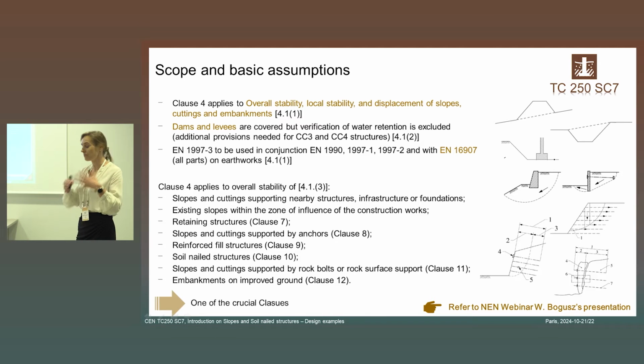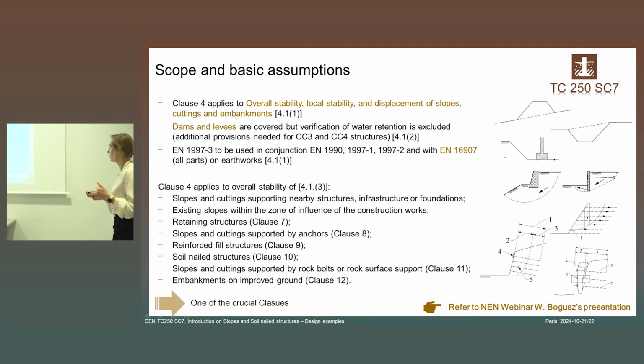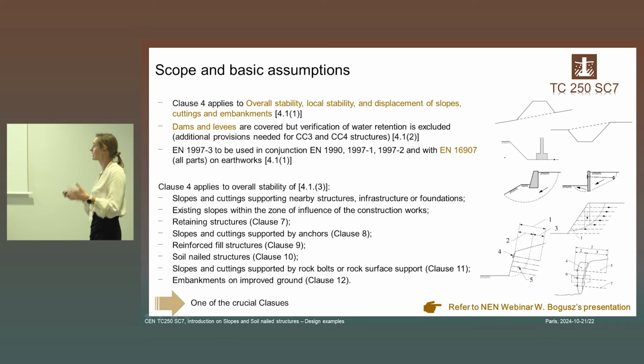About some basic assumptions, clause 4 applies to overall stability, local stability, and displacement of cuttings and embankments. It covers dams and levees, but under specific conditions, as verification of water retention is excluded, and we also should remember that in consequence class 3 and 4 we may need some additional provisions.